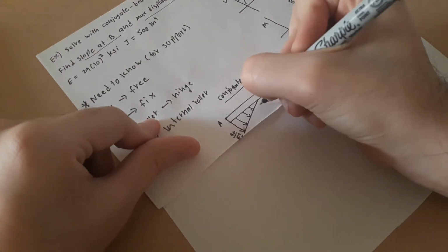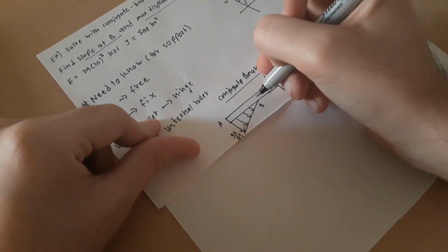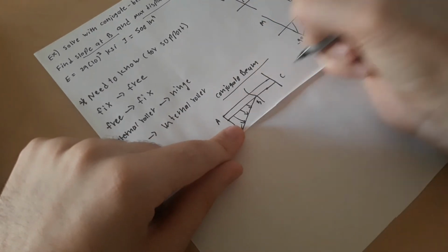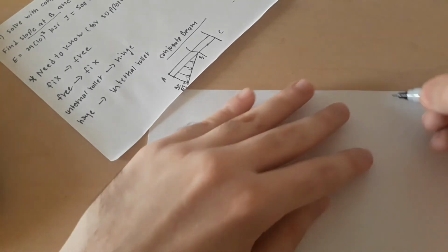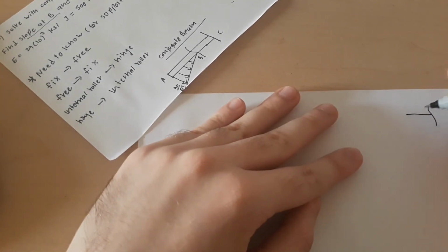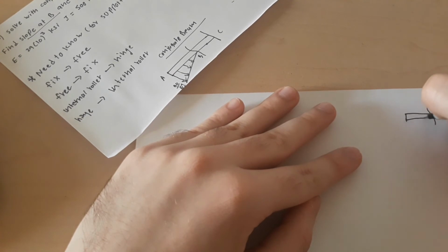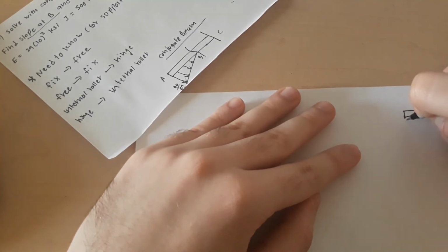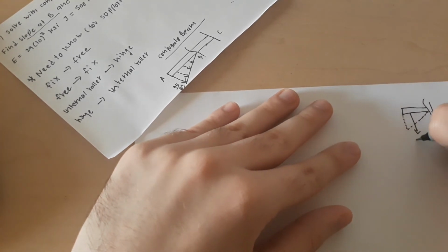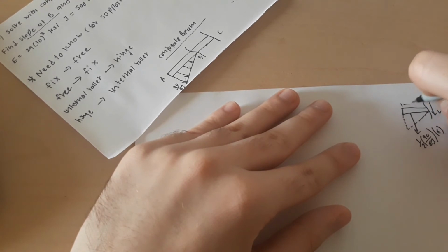So the slope at B, right here was A, B, C, right? The slope at B is the shear at B, so we cut it. I'm going to redraw it right here. So cut like this. So V, right? And then it's right here. This comes down. This is 1/2 90 over EI times 6, since right here was 6 feet.